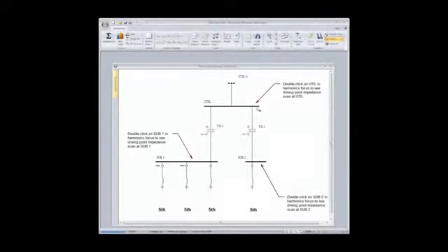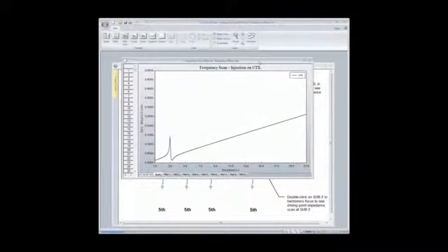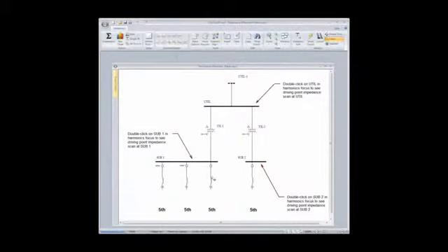So the point at which we are wanting to discern what the driving point impedance looks like really depends on where we are and where we're looking. And this brings up one of the key points that I want to drive home, and that is impedance buffering. If you're going to apply a notch filter of any form, you have to have some form of impedance buffering to isolate you from the rest of the system that you don't want to see your fifth harmonic filter.